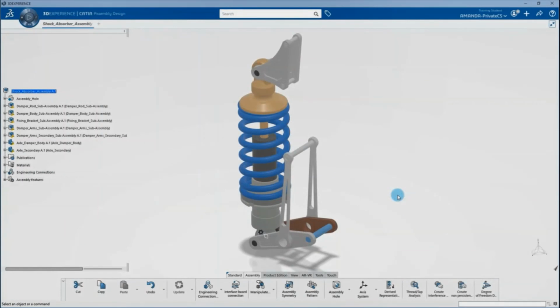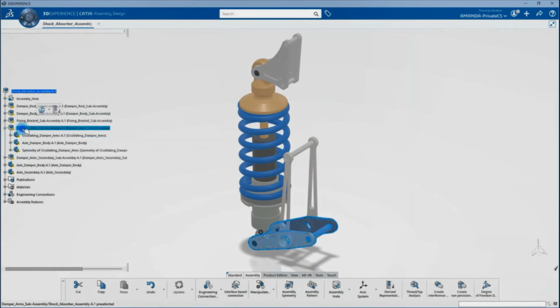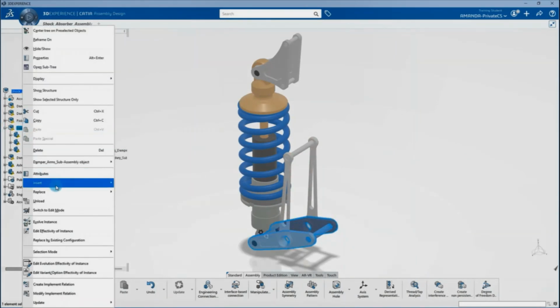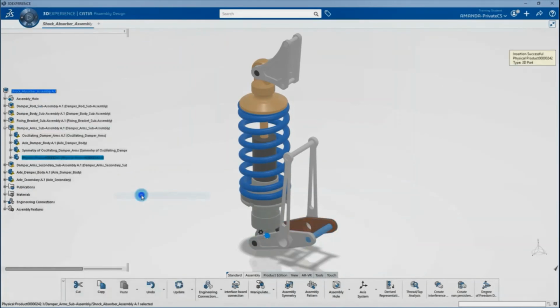Generally, interfacing parts are designed using references of elements from one another. This creates a dependency of dimensions, which makes it easier to modify the parts when needed. This is called designing in context. We will design the central axle by taking external references from other parts. We will insert a new 3D part into the sub-assembly.